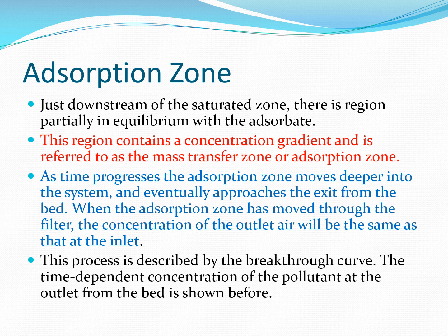So the adsorption zone, I think these are points I already discussed. Just downstream of the saturated zone, there is a region partially in equilibrium with the adsorbate. This region contains a concentration gradient and is referred to as the mass transfer zone or adsorption zone. As time progresses, the adsorption zone moves deeper into the system and eventually approaches the exit from the bed.